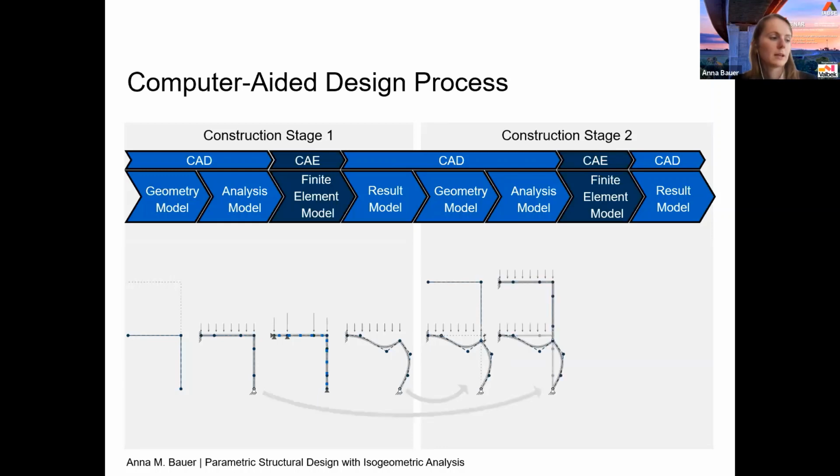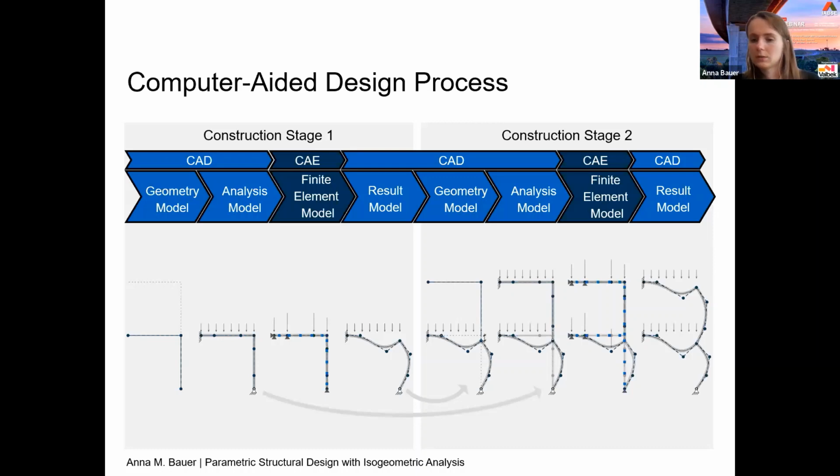And again, we can also link the analysis model to the first model by telling the lower part of the deformed geometry, okay, you've been initially straight like in the beginning here before. By that, we can also transfer the information that this is not the first step, but the second step in the analysis tool chain. Having that, we just generate the FE model again, and we get the final result of this two-story frame.